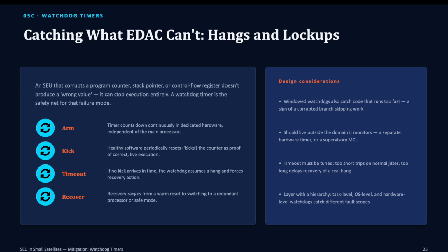The timer counts down continuously in dedicated hardware. Then a healthy software periodically resets it. If no kick arrives in time, the watchdog will assume a hang and then force recovery. The recovery ranges from a warm reset to switching to the redundant processor or safe mode. So watchdogs basically protect against a corrupted program counter that stops execution.